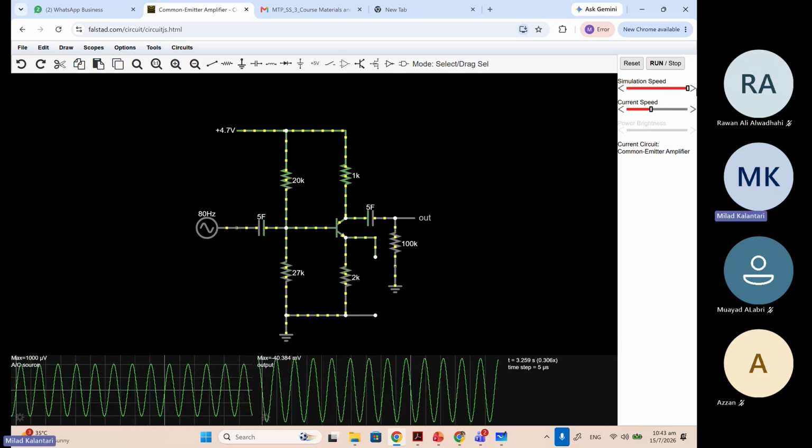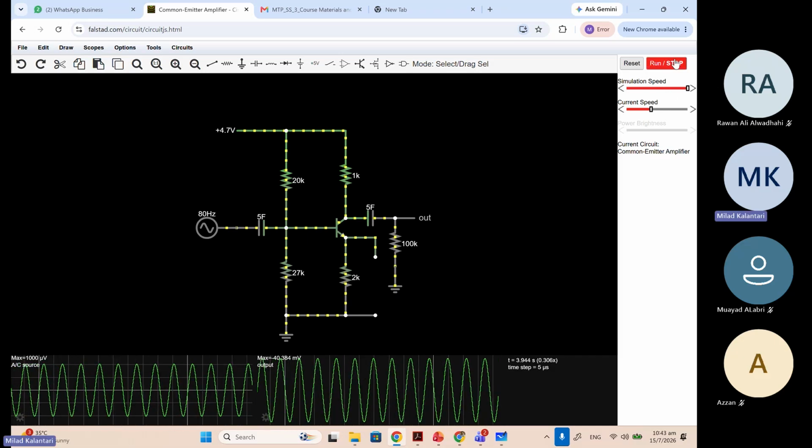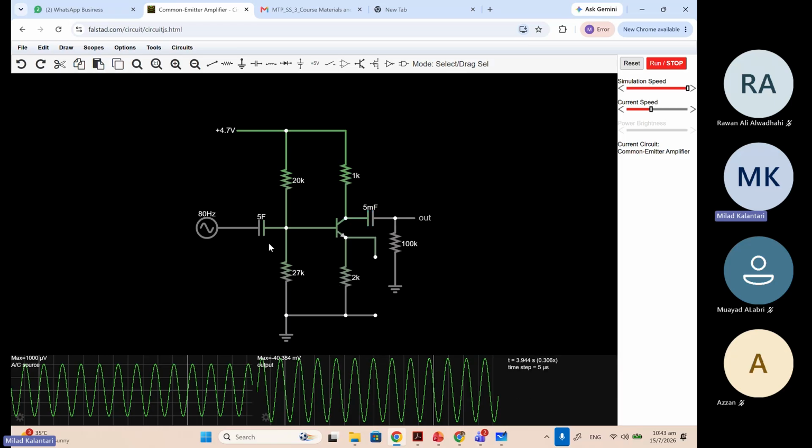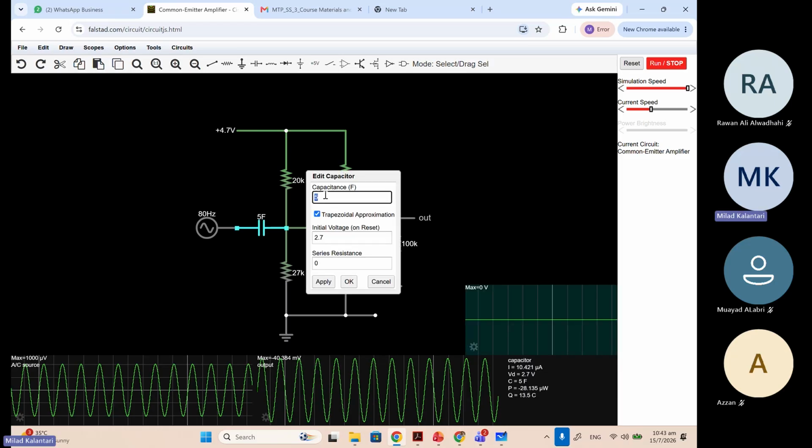No, still too slow. Actually, I know what is happening. I put a large cap, but the cap takes some time to reach the final DC value. The cap is so big, it is impractical, in fact. So I reduce the cap value, see how it will be.